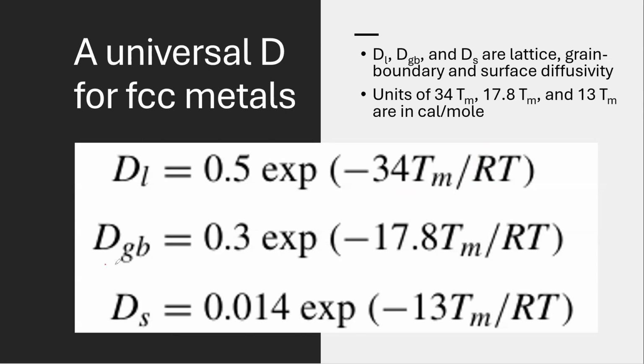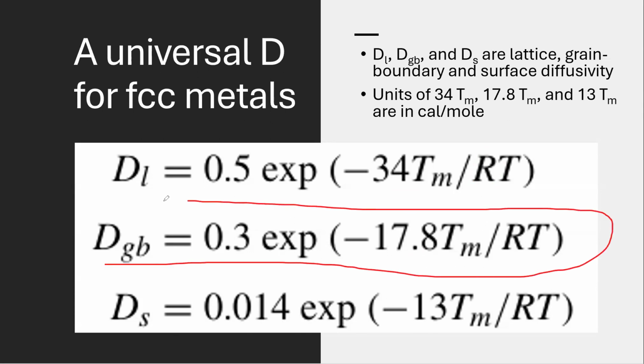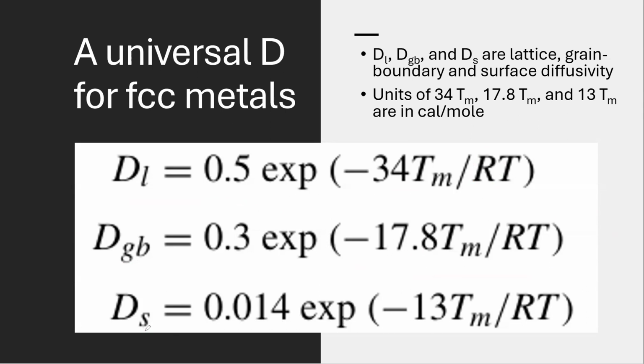Right now, people focus on the grain boundary because the surface has been protected and covered by something. So you pretty much don't have surface diffusion anymore unless you're exposed, then you have a problem. But usually they're capped, sandwiched by an adhesion layer and a diffusion barrier, all kinds of layers that protect the metal of interest from exposure to oxygen.